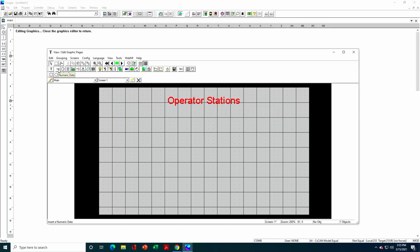We've got numeric data objects. We've got a timer, time objects, a whole variety of different objects, switch objects, selector switches, sliders, jump buttons, bar graphs, etc. I know I'm not spending any time on these objects, but again, this is a quick getting started guide. So we're going to start with an indicator, and that indicator is just the equivalent of a pilot light that we're going to use to turn on when our motor starter is running. Okay, so what I did there was I clicked on the indicator, I clicked and dragged to the size I wanted approximately, then I let go.